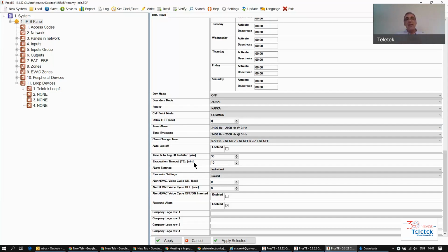Again, I'm going to give you an example in order to better explain what time before general evacuation means. Imagine you have a 5-floor building and each floor is a separate zone. It's zone number 3, respectively, floor number 3. There's fire. Now we want to evacuate the people from zone number 3 before the other floors, because this is the problematic zone.